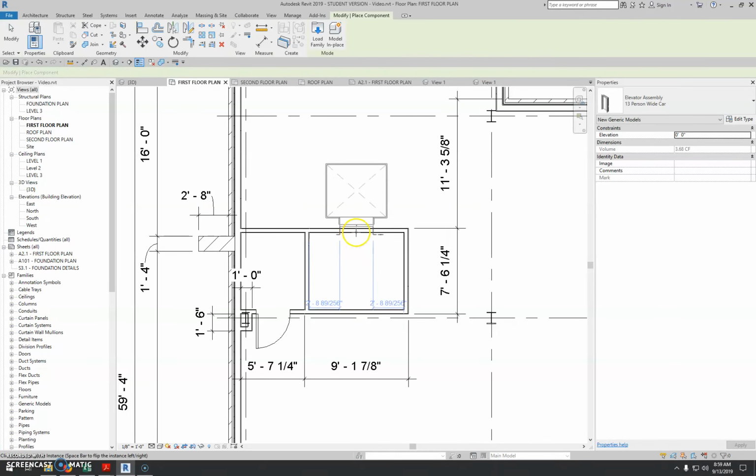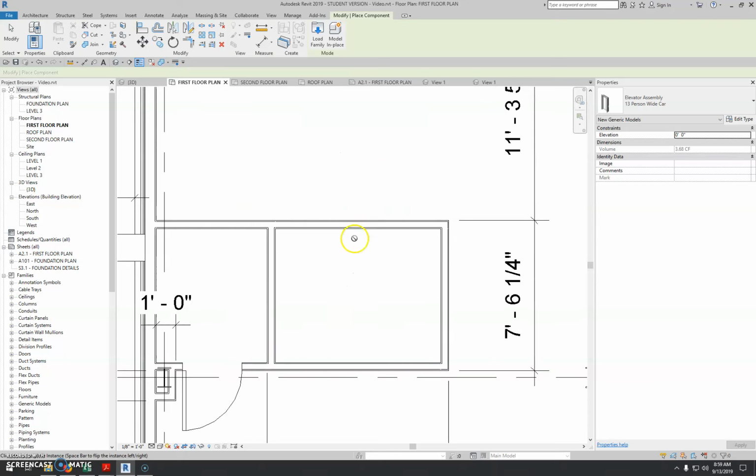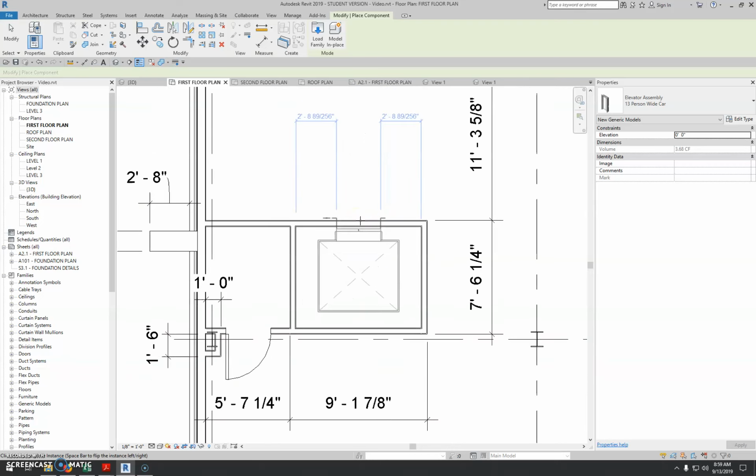and simply find a wall. It's a wall-based family, so you can't place this out in the middle, so you have to have a shaft for this. Depending upon how you hover over this thing, it'll place that element. And you can see that my temporary dimensions are equal, so that is centered in there. And that's exactly where I want to place this.